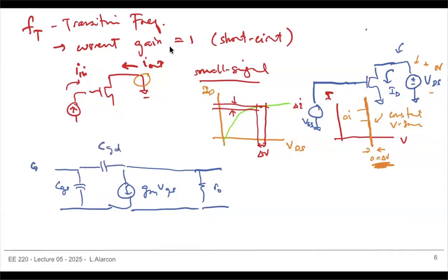It's a gate, source, and drain. So just to be clear, this is what you need to get this small signal. I need a VGS and I need a VDS. It gives me an ID. So once I have all those, I can actually start to calculate this gm, this rout, and I can estimate what CGS is and what CGD is.